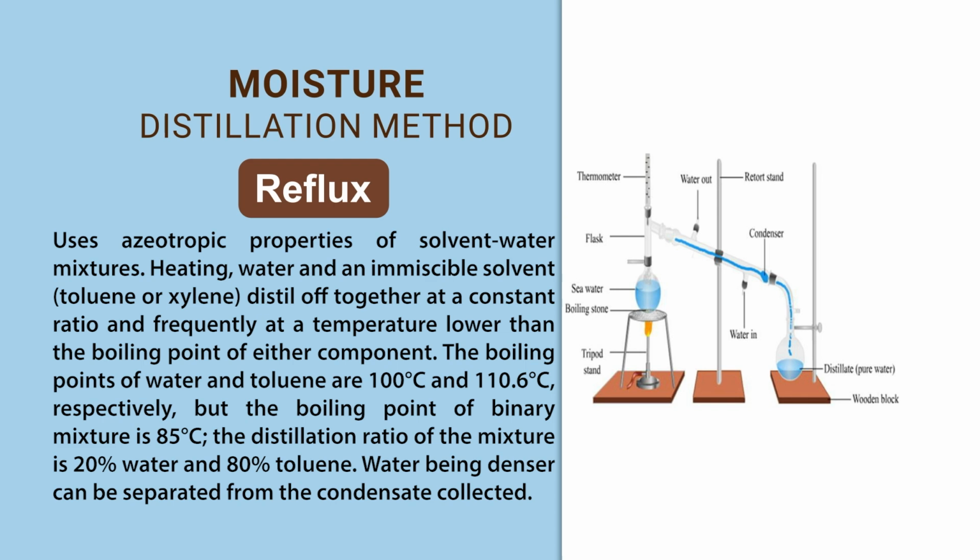That is almost like reflux boiling, where solvent will fall back, and you are collecting the solvent plus water; because water is heavier, it will settle down, you separate that out, and the solvent again remains there. So this is by way of using a non-polar solvent to remove water. This is done, for example, for all sorts of oils from oil seeds. The extraction is done to remove water. This is the way it is done.